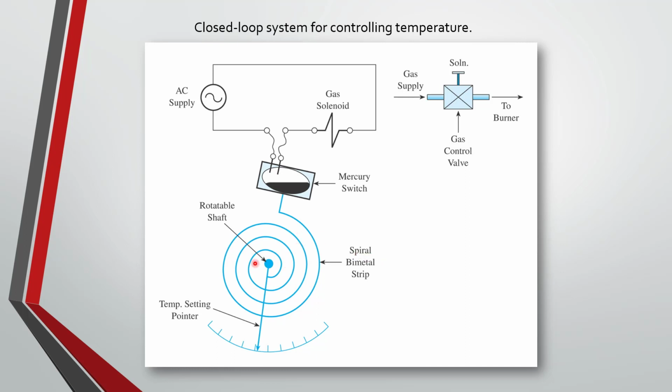So in this case, in this coil made out of this type of material, as this cools, it's going to contract, and as it heats, it'll expand. So as this expansion occurs, this will tend to rotate this direction. This is a rotatable shaft here. And as it cools, it'll tend to tighten up, causing that to move this way. So I can preload or put some tension onto this spring that positions this somewhat. And then it can also be positioned as it cools, contracts, and expands.